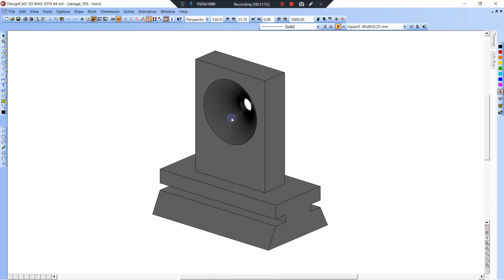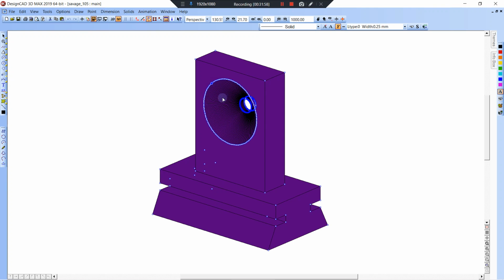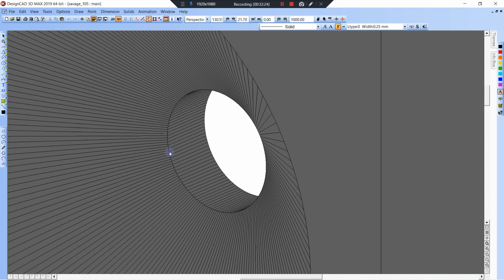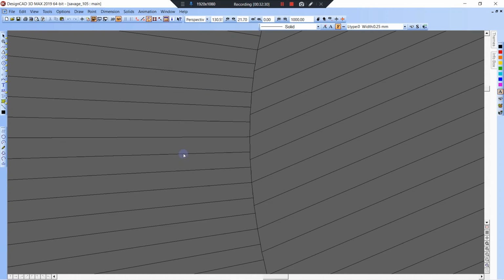When you draw, let's say you were drawing something that had this frustum or cone, well, you see the amount of things that are in there. If you were going to attach a cylinder to that, you want to match up so that the cylinder has the same number of nodes all around the perimeter. It's not that hard to do. This one's probably 128 count, and once you get to using it, you kind of understand. If you zoom in here, see those right here, this circle, it looks like every third one. If we started there, 1, 2, 3, they match. 1, 2, 3, they match. So that works pretty good.